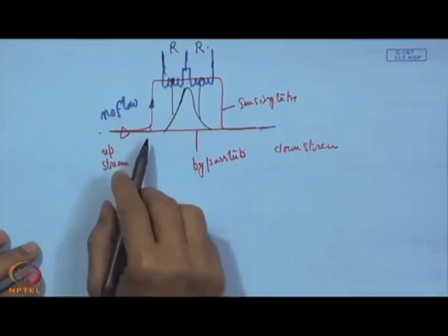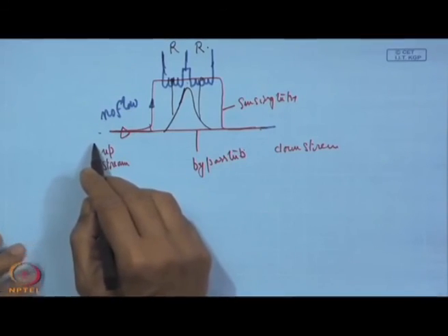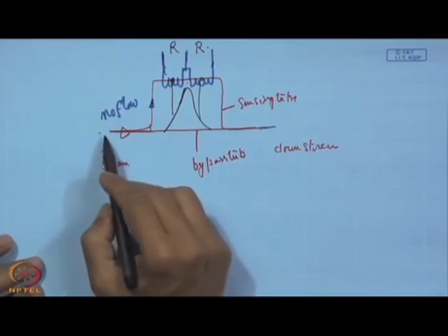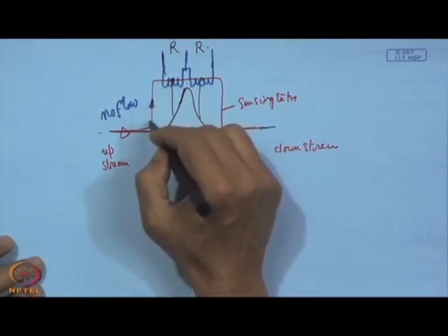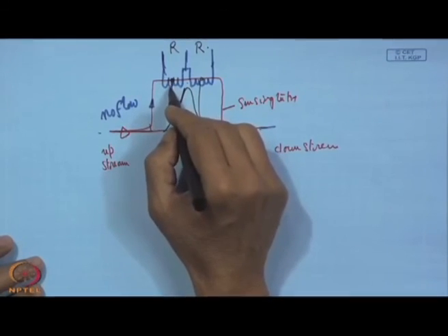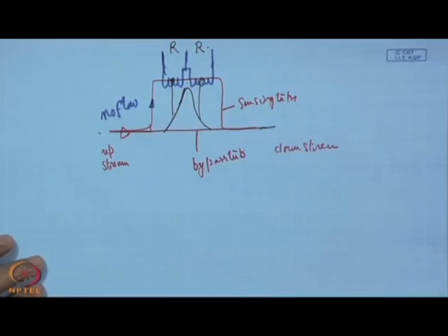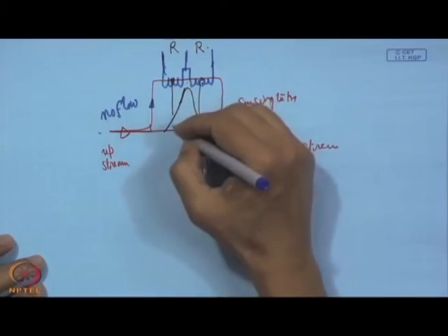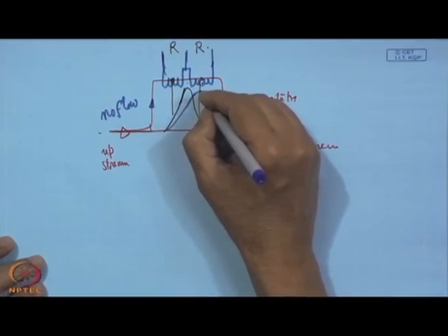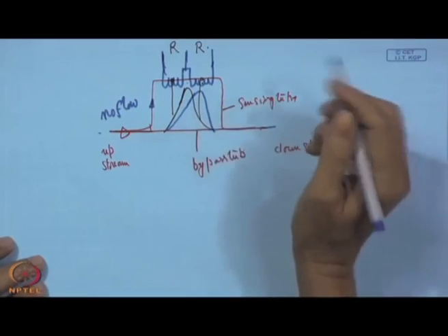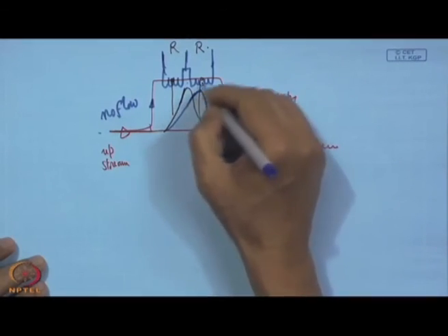However, when the flow is switched on, because of the heat capacity, heat will be transported. The heat will be taken by this flowing gas from this heating element and delivered on this side. So, when the flow is on, this temperature profile will be shifted towards the downstream side, and what is shown by black is no more in existence and it is more of a blue.